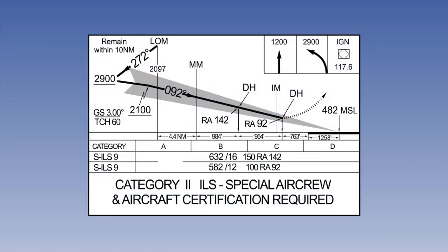First, we must define low visibility procedures. They are aerodrome procedures to ensure safe operations when non-standard instrument approaches and departures will be conducted. These non-standard instrument procedures are during lower than standard Category 1, other than standard Category 2, Category 2 and 3 approaches, and low visibility takeoffs.